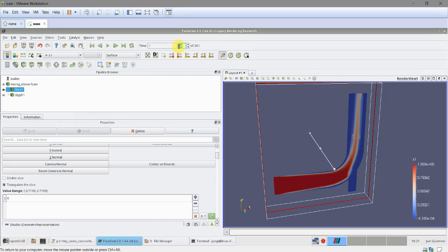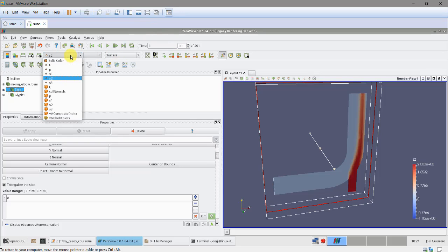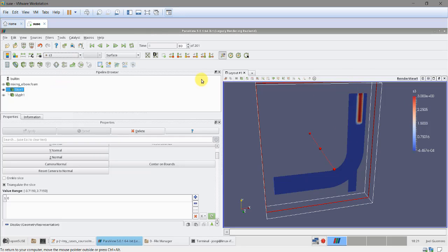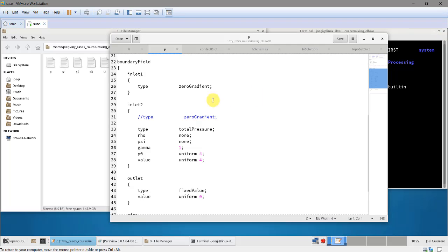So if I go to time 80, I think that all these scalars reach this point, so we can see how everything is mixed, and then also I can control the concentration in the outlet. And I think at time 80, I switch off this scalar. So if I go to 90, you see, yes, here I switch it off, and now we don't have any more scalar in the domain. So you have a lot of control when it comes to a source, fvOptions, which we're going to talk about.